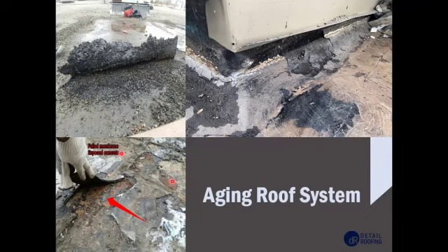That means the membrane is covered by insulation, filter fabric, and gravel, so all of this damage can't be seen unless you remove all of that and expose the roof system. Once the membrane starts to fail on an inverted roof system, you'll have the insulation sticking, and in this case it's coming up to the point where you can see the concrete deck below. In all of these cases, multiple leaks were occurring at these buildings, and it is time for replacement.